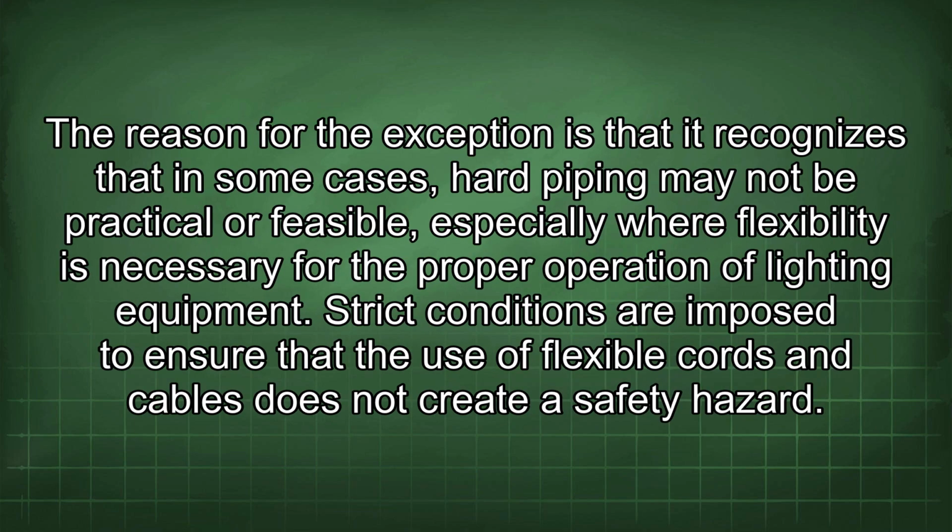The reason for the exception is that it recognizes that in some cases hard piping may not be practical or feasible, especially where flexibility is necessary for the proper operation of lighting equipment. Strict conditions are imposed to ensure that the use of flexible cords and cables does not create a safety hazard.